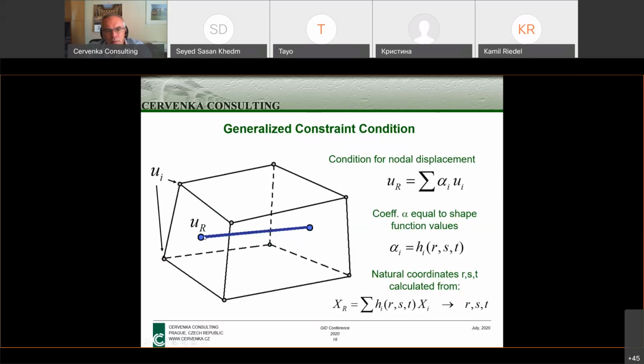And this is done by adding additional degrees of freedom to these reinforcement nodes. And this additional degree of freedom represents slip. And then we can directly use a slip law given in the codes or measured in the laboratory to simulate the bond failure between concrete and reinforcement. And this approach gives us also another possibility, which I will show in the next part of my presentation today. We can also use it to simulate pre-stressing losses.